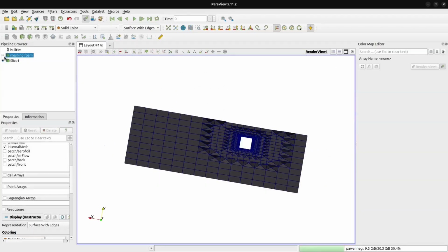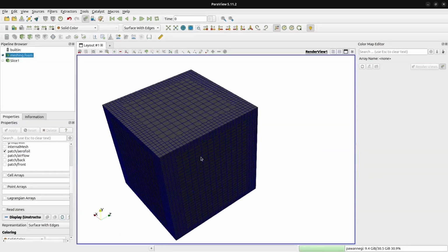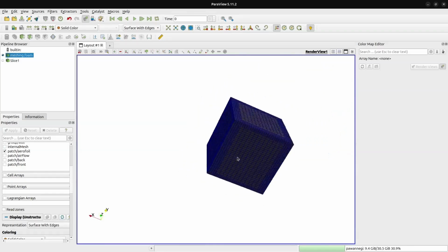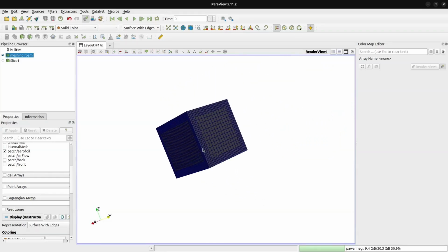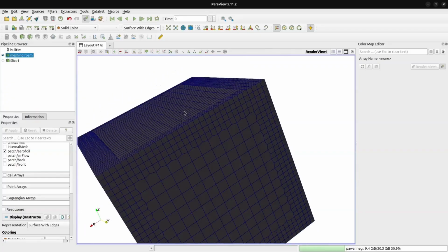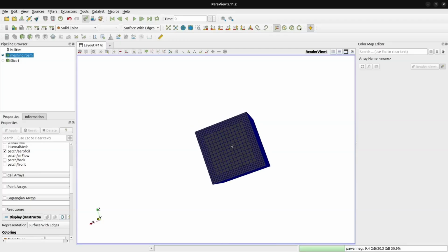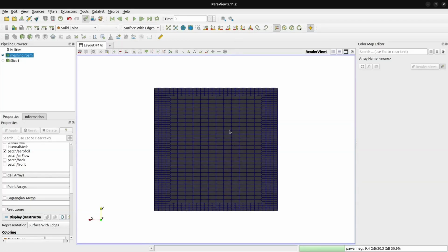Let's also look at the surfaces only. Let's just look at the surface of the cube. You can see that the mesh is very good. The edges are nicely resolved and everything looks good. Looks like SnappyHexMesh works very well with this kind of sharp geometry. But here is the truth, that it does not. The fact that it worked here very well is because this particular geometry is aligned with the Cartesian grid.